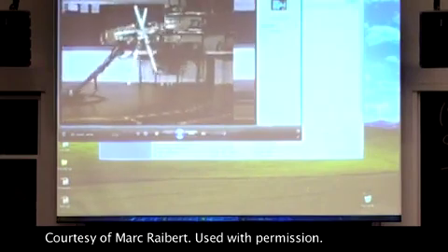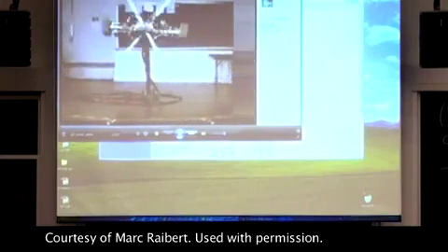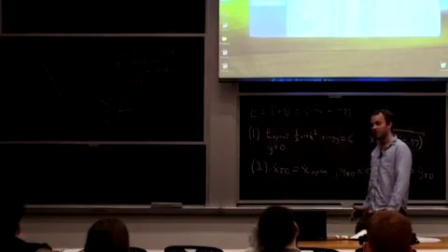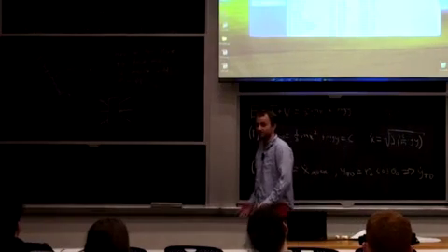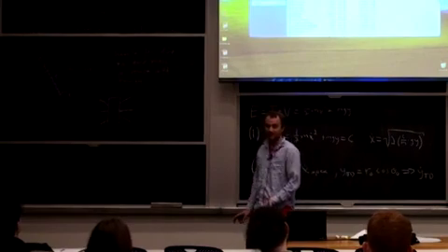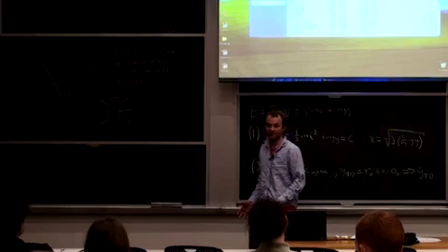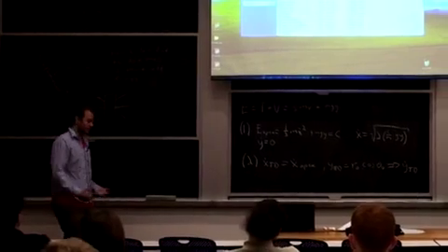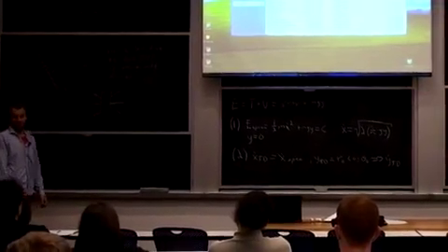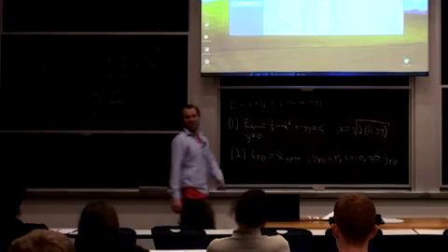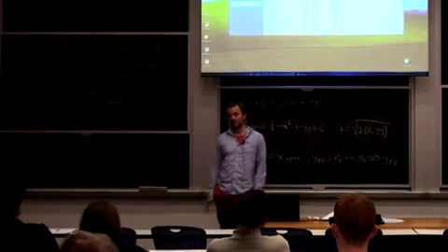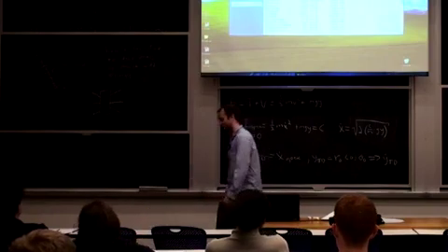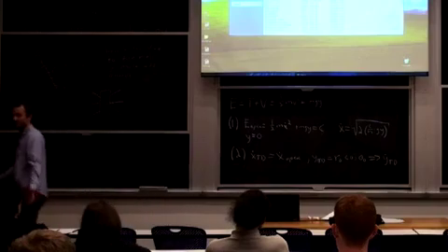Something that people are working on more recently is this thing called slip walkers. You can imagine if you have a compass gait with springy legs, right? As its spring constant gets very high, it starts behaving just like a compass gait. If the spring constant goes to infinity, it's rigid, it's going to be just like a compass gait. If you let those springs get looser and looser, it's going to start being more like one of these bouncy bipeds, more like this kind of slip behavior. And so actually you can get stability properties. It can be stable through a relatively broad range of bounciness, so that the same robot can vault over its legs and walk and then start bouncing and running.